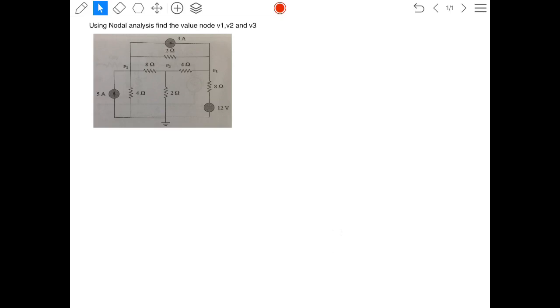different nodes here. So for those who are not clear how to define the nodes, you need to make sure it is non-identical nodes. As you can see here, this junction and these nodes and junction actually have an equal potential, and thus all these are equal to a single node. Same goes to this point, and also this junction, this path.